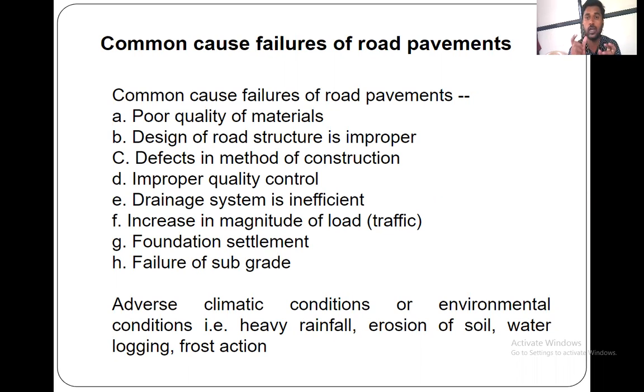Also, we need to check the soil, the CBR value of the soil. As we go deeper and deeper, we should have more CBR value, so the subgrade, being at the bottommost layer, should have the maximum CBR value compared to all the other courses or layers. The base soil should have the higher CBR value. Likewise, all the tests we need to carry out on each and every material that we are using here, also in the concrete road as well.